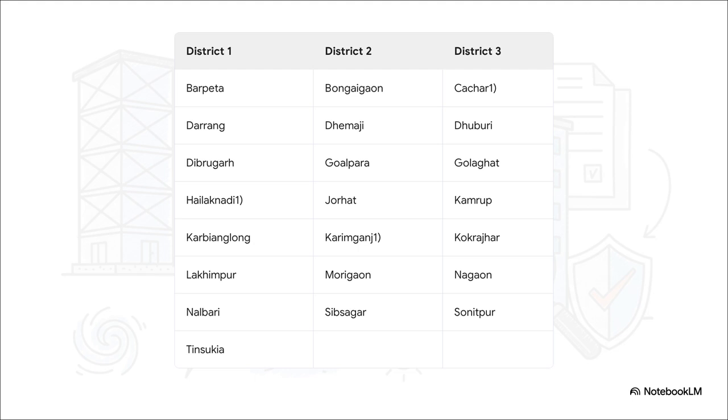Let me give you a real-world site scenario. Misaligning your reinforcement bindings during a hectic concrete pour. It happens all the time, right? Well, in these zones, that common installation error severely compromises the structure's seismic resilience. You literally cannot afford that mistake here.